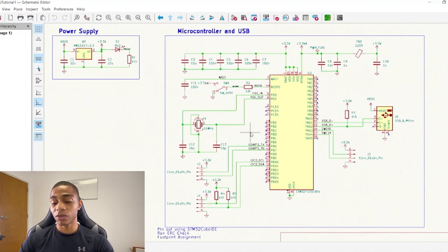So I know what Phil had us do is we just attached a line or a signal to it, and then we added a capacitor, and this capacitor will attenuate high frequency noise, sending it to ground, so that we don't inadvertently trigger our reset, our nRESET signal. All right.